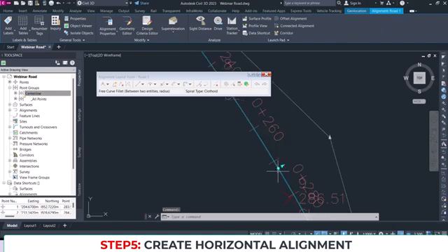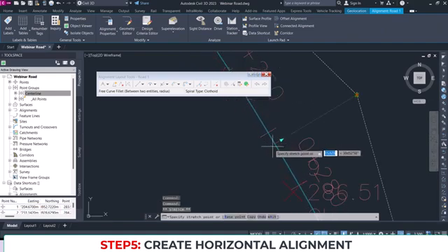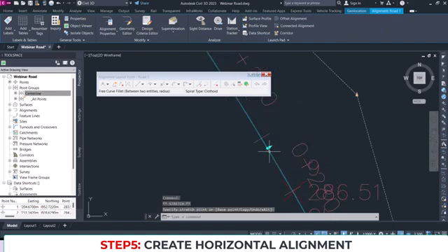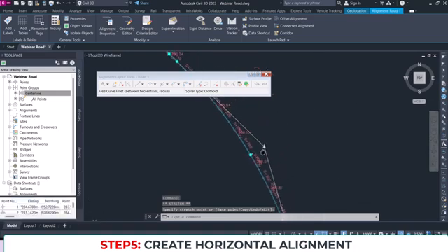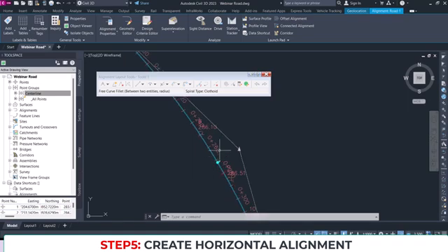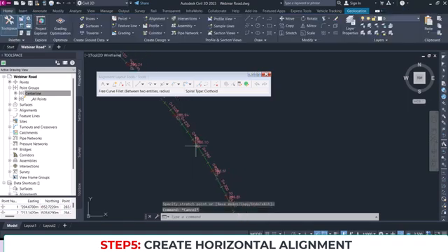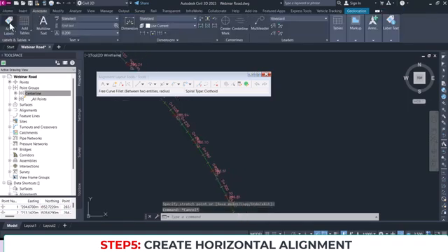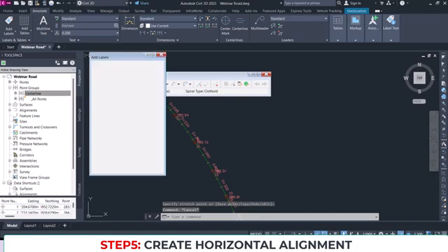So we can drag it. You hold this circle and then draw it backwards. In that case, it will increase the curve radius. If you want to see what radius you have just done by what you have dragged, you can go to add a label. Okay, and the label I'm adding is an alignment label.